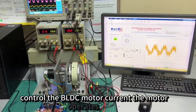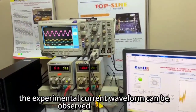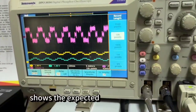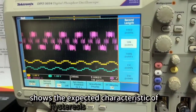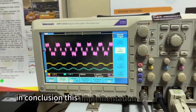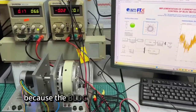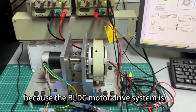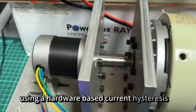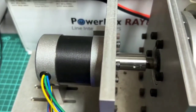The motor operates stably, the experimental current waveform can be observed in real time, and the current response shows the expected characteristic of hysteresis current control. In conclusion, this implementation fulfills the assignment objective because the BLDC motor drive system is successfully controlled using a hardware-based current hysteresis controller, not only through simulations.